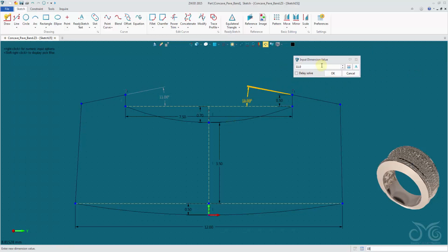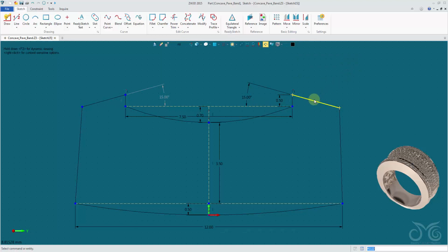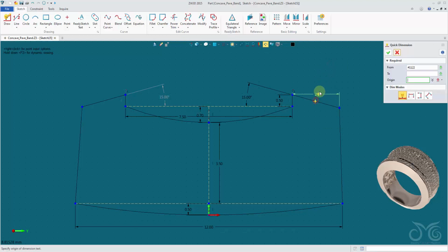Okay. Finally, we'll add a length constraint to this part of our wall. Right click, quick dimension. Okay, now you can see how there are two types of dimensions we have here. We can sift between them. I want the aligned dimension. Okay, I do not want the horizontal. This is the horizontal. I want the aligned one, this. Sometimes you may have trouble picking between them. You can just select it from here. Okay, so it's aligned.